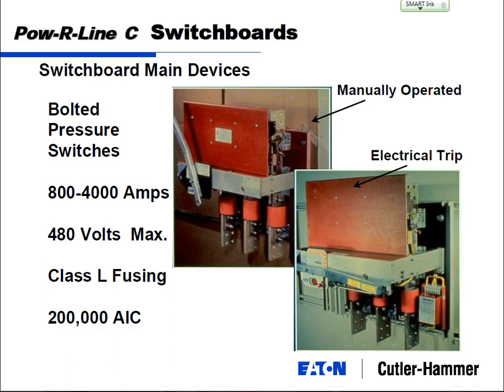Talk about service entrance, which we'll come on to. Service entrance is going to require ground fault. Ground fault protection is going to require the main device to trip. So if you get in a case where your service entrance needs ground fault, you immediately jump up to an electrically operated device if you're looking at a fusible switch.